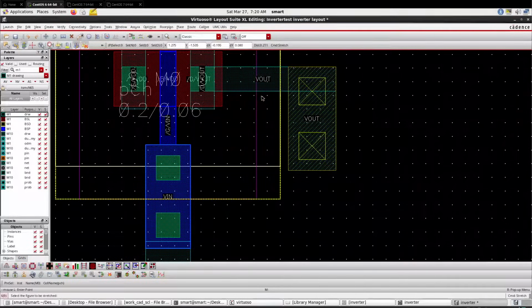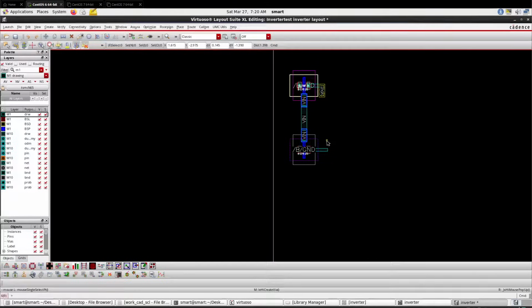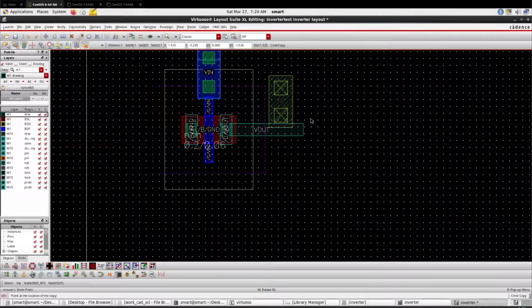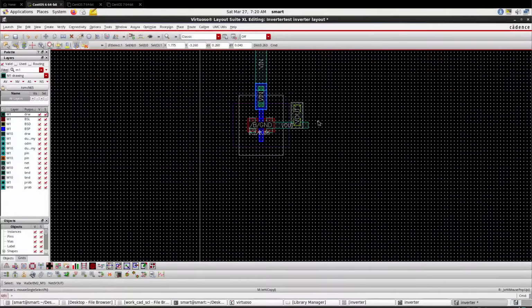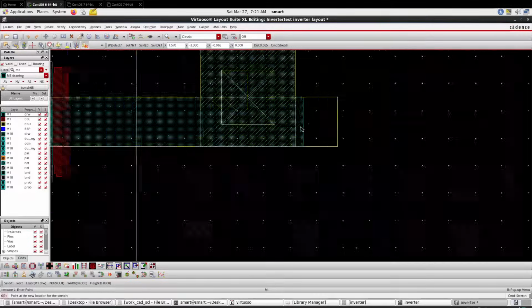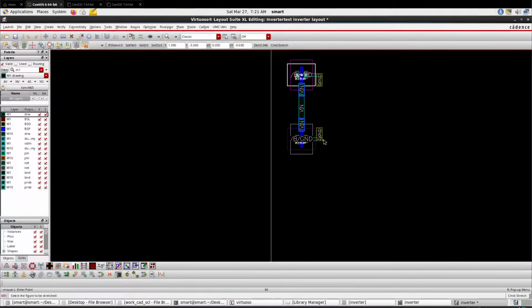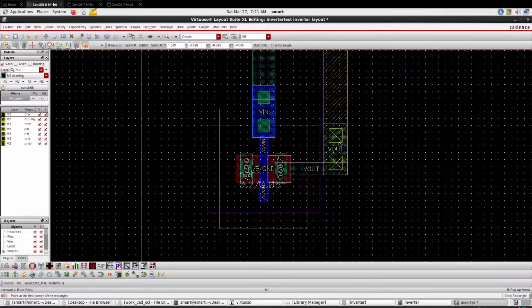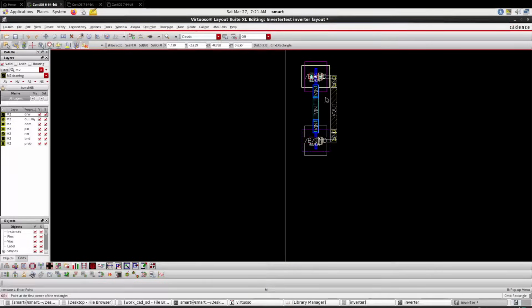Okay, next, press C for copying the same thing if you need. Next press S to set the layer according to the via. Now use M2 to connect this output node. In layout, alignment is very much important. Keep your instances in proper alignment.